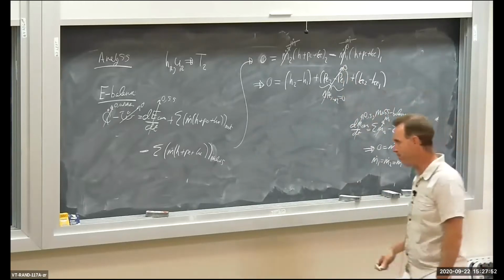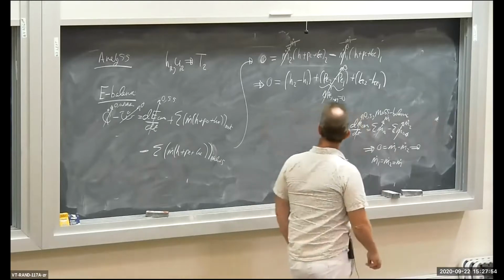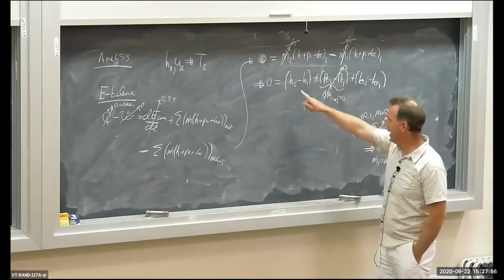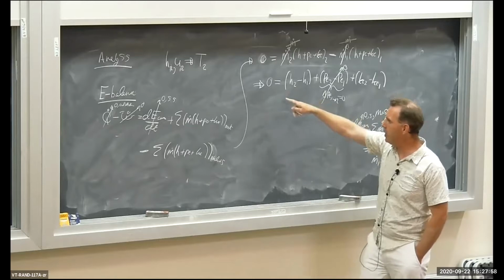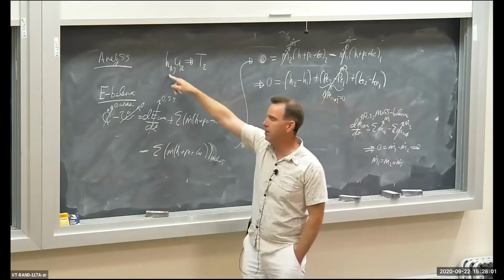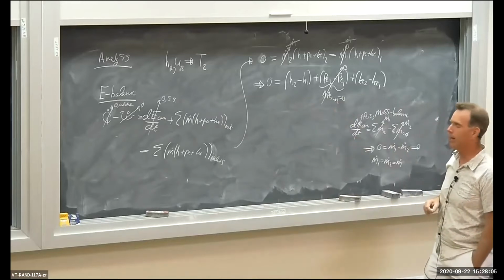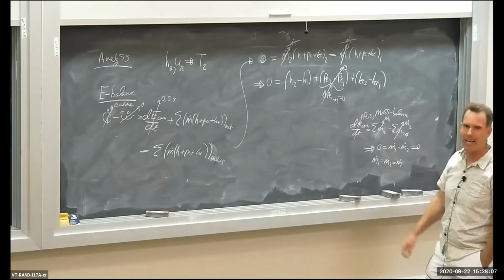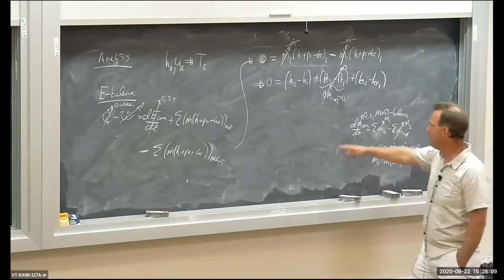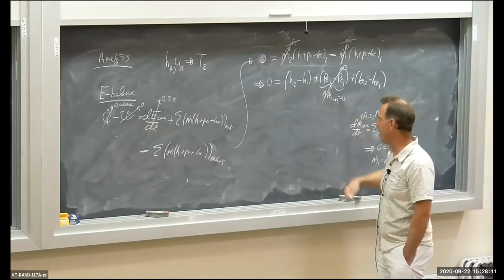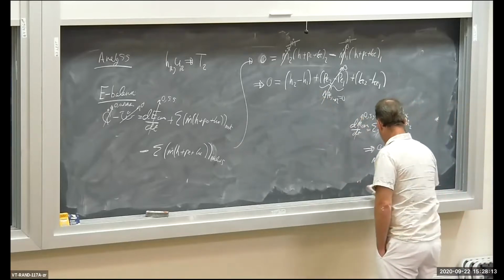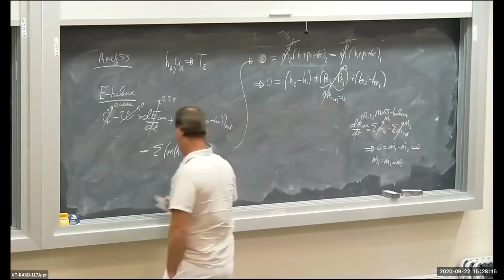All right? Now I want an outlet temperature, which means I really want an outlet enthalpy. If I get the outlet specific enthalpy numerically, I can go to an air table and back out a temperature. So let me solve this resulting equation for H2, the outlet specific enthalpy.